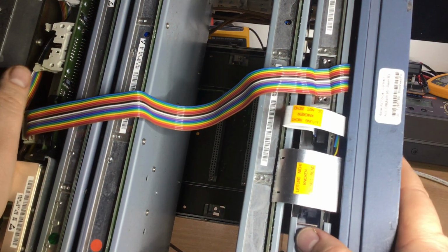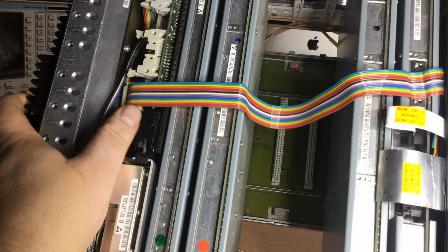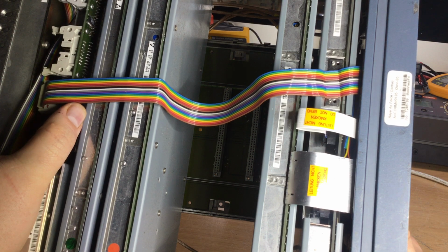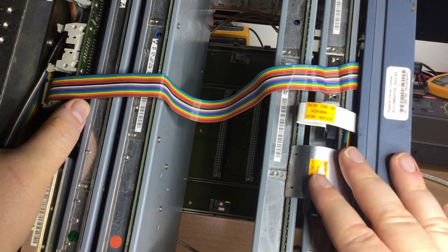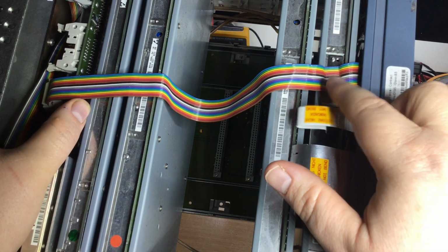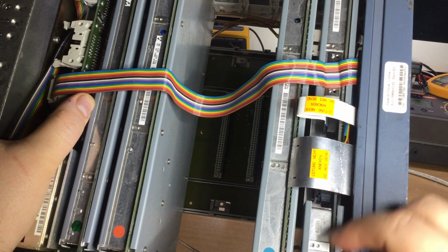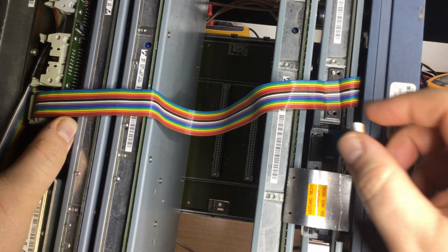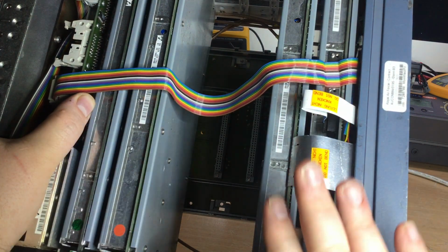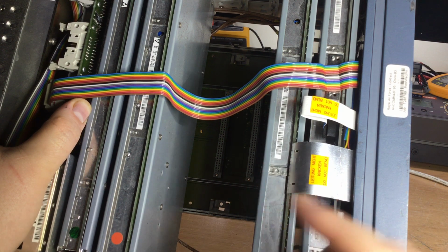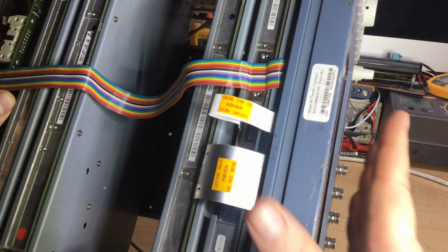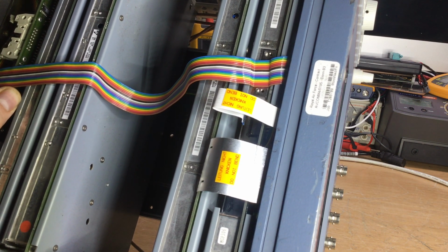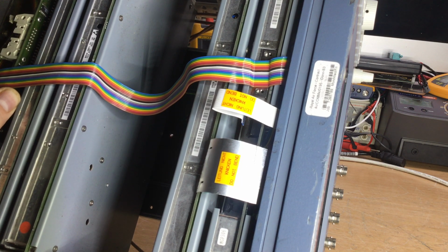So we basically got 2 flexes here which lead off to the display and the keyboard, and then we've got this ribbon cable which goes to the back, which connects to the rear board here, where I think it gets some more digital in and out on that flex. So I've disconnected a bracket that was here. We've removed these connectors. Quite a simple process of just backing these catches off and letting the flex come out, so that we can remove these two modules, because if I can get to the rear of the display unit without having to remove the front, then that will be a big advantage. So I'll just flip it over on the other side and then we can take a look at its underneath.